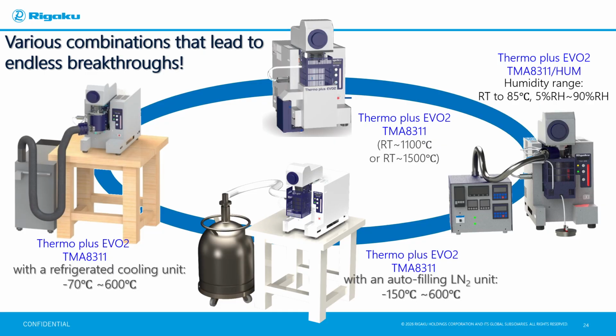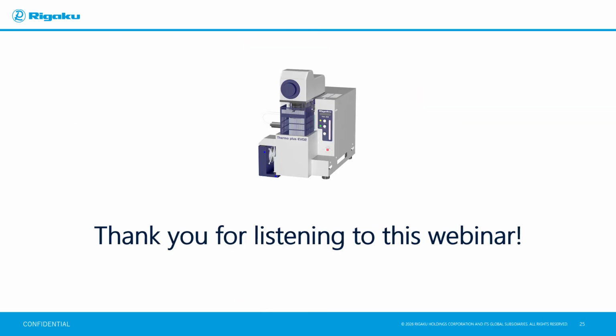Our TMA 8311 can be used standalone, when you can measure from room temperature up to a maximum of 1500 degrees Celsius. It can also be connected to a cooling unit, such as the refrigerated cooling unit, for measurement ranges from -70 degrees Celsius to 600 degrees Celsius, and the auto-filling liquid nitrogen unit for measurements ranging from -150 degrees Celsius to 600 degrees Celsius. We can also run measurements under humidity-controlled atmosphere conditions of room temperature to 85 degrees Celsius and 5% to 90% RH. So, thank you for listening to this webinar.